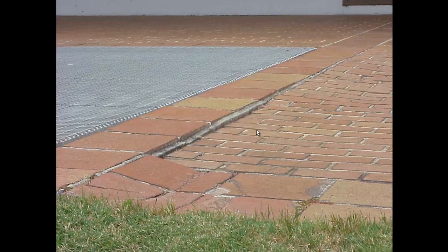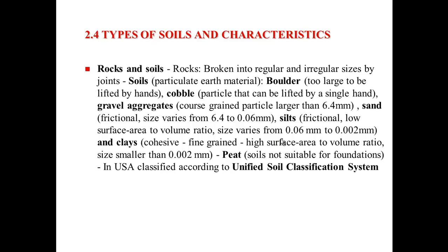So in addition to just the soil's capabilities, frost is something that in this part of the country we also need to think about as part of that differential settlement equation, and making sure that we're below the frost line. In this area we're looking at 4.5 to 5 feet depth to get below frost. Other areas of the country may be much less or none at all, but certainly designing to your climate is another important factor in your foundation.